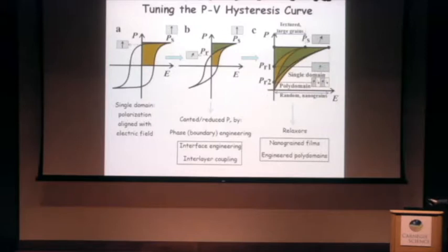And when you charge this film, of course, one set of the domains will be favored, but this is at the cost of removing the domain interface. So it's very difficult to be saturated. At the same time, if you discharge, because the head-to-tail remnant configuration is stable, you can get close to zero remnant polarization. So this kind of structure is very good from a dielectric capacitor point of view.